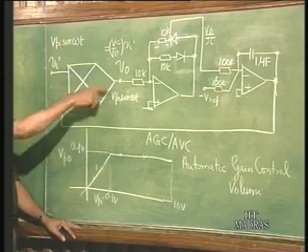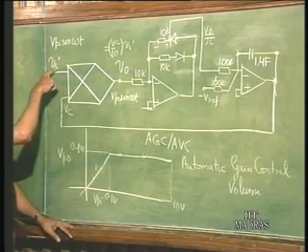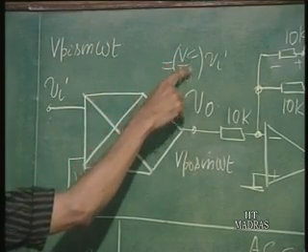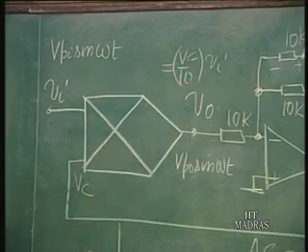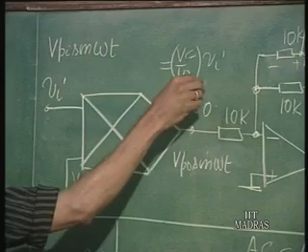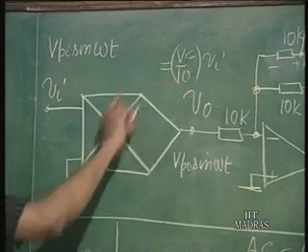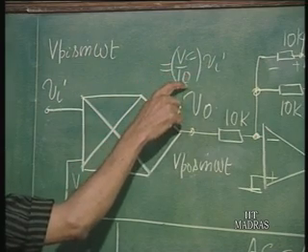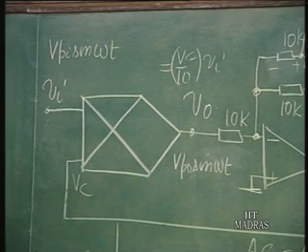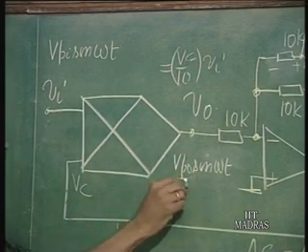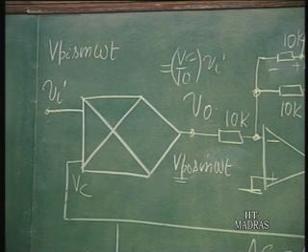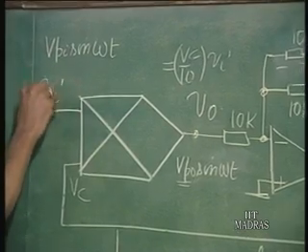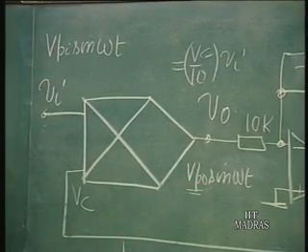So, this is the multiplier whose input is V I, and if the control voltage is V C, it will have a gain of V C by 10 into V I, that we have understood. What is done is V C is adjusted by this control loop such that V C by 10 into V I remains constant at a specific value. That means V P naught, after a certain point, remains constant independent of V P I. V P I sin omega t is the V I and V P naught sin omega t is the output.